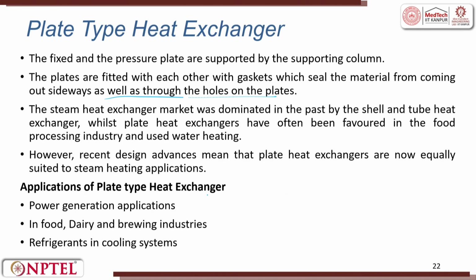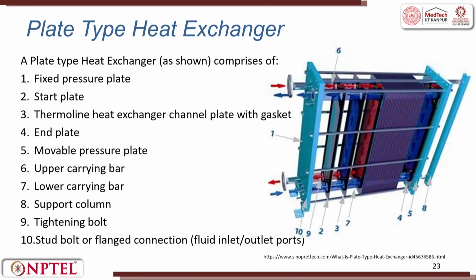The applications of plate type heat exchangers are power generation and the food, dairy and brewing industry. Refrigerants in cooling systems also use plate type heat exchangers. So, this is a typical plate type heat exchanger. You can have moving pressure plates, an upper carrying bar and a lower carrying bar. The upper carrying bar and lower carrying bar are to guide them.